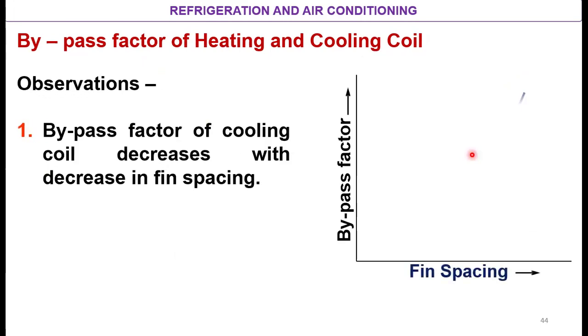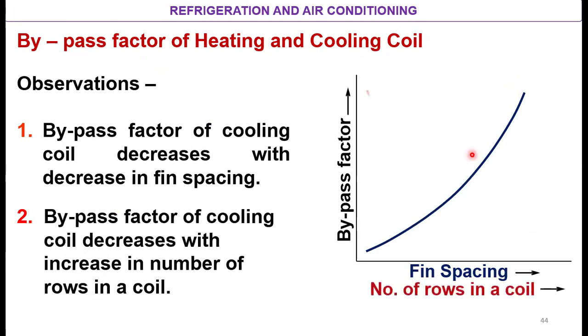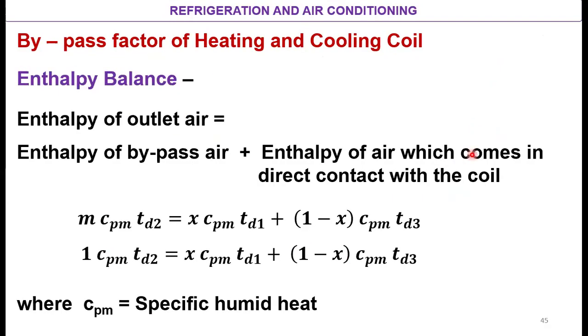Okay. The bypass factor decreases with the fin spacing, and the bypass factor also decreases with the increase in the number of rows of the coil. And by appropriately applying the first law of thermodynamics or the energy balance, you can calculate the bypass factor.